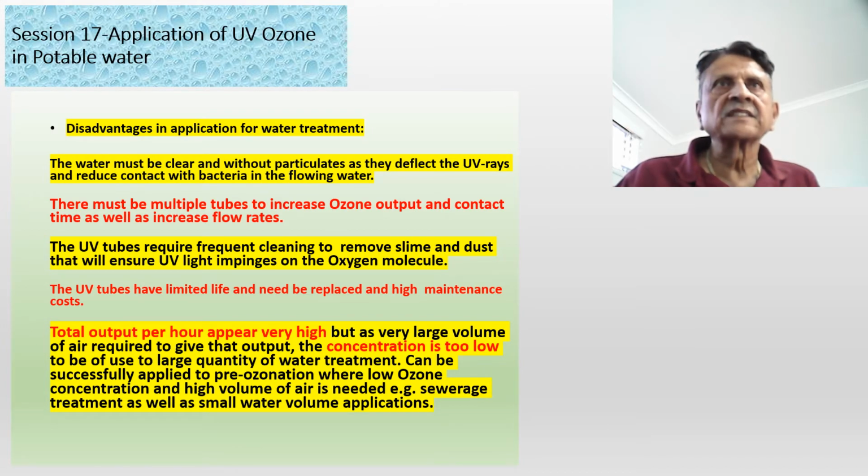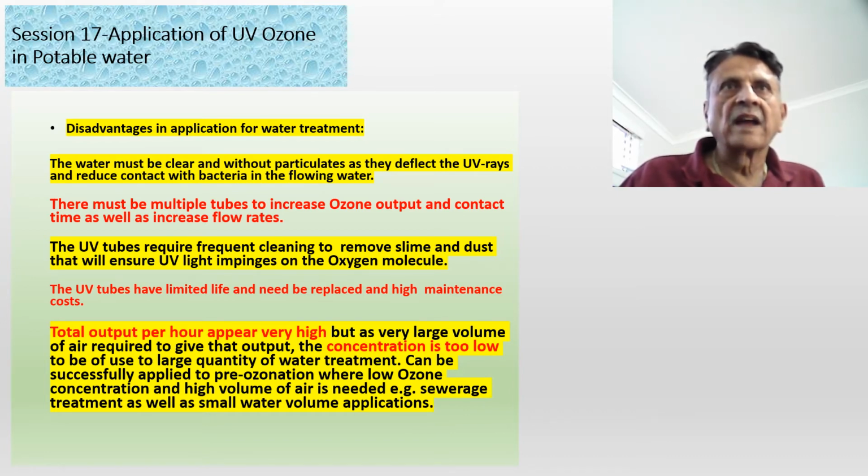The disadvantages in application for ozone treatment using UV. The water must be very clear without any particulates, as they also can deflect the UV rays and reduce the contact with the flowing water. There must be multiple tubes to increase the ozone output and contact time as well as flow rates.